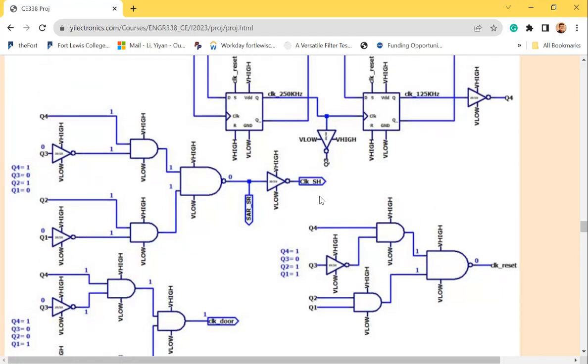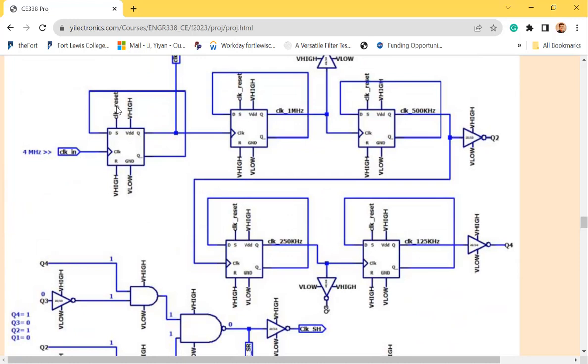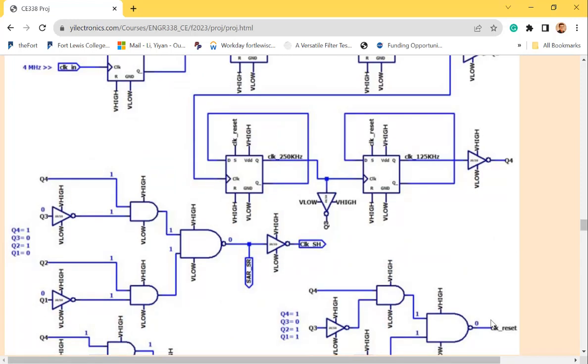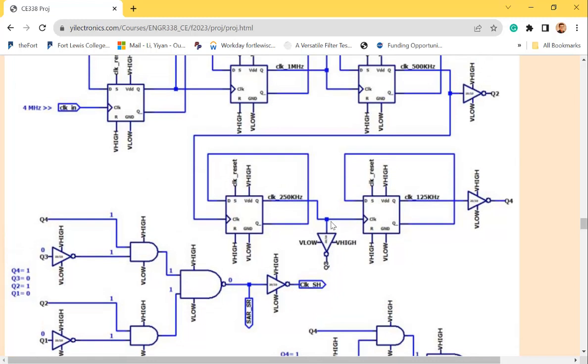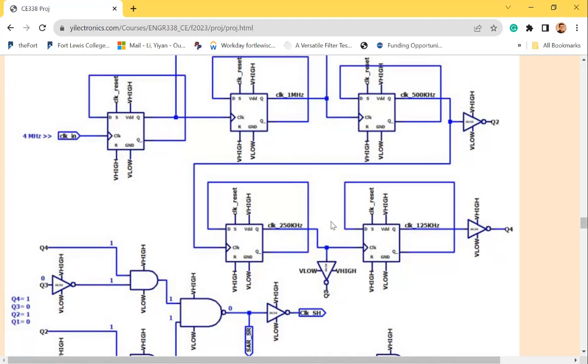So if you see clock reset, I believe it's connected to here, see? That's all the D flip-flops of the counter. It's active low, so it's setting it, but we are using Q bar, so it's actually giving zeros to everything, right? Or even though we are using Q, we invert it, right? So eventually it's still 0. After this one is getting set, Q is going to output a 1, it's going to invert it, outputting a 0. So all the outputs of the counter become zeros. So the counter will start from 0 and keep counting up after that.